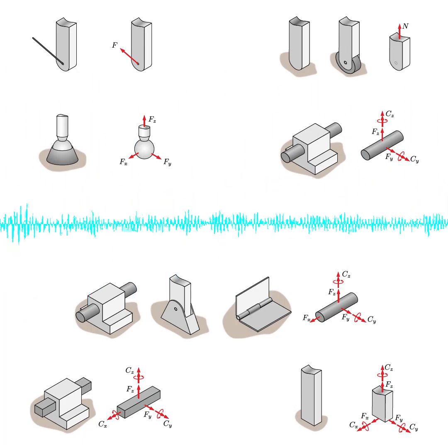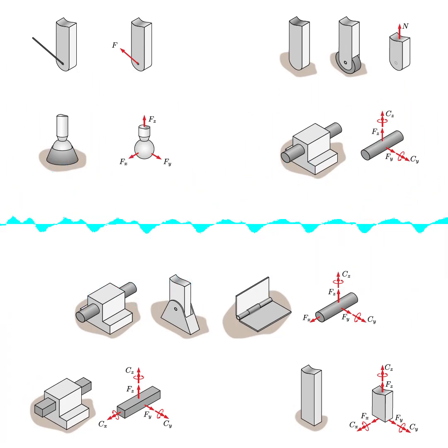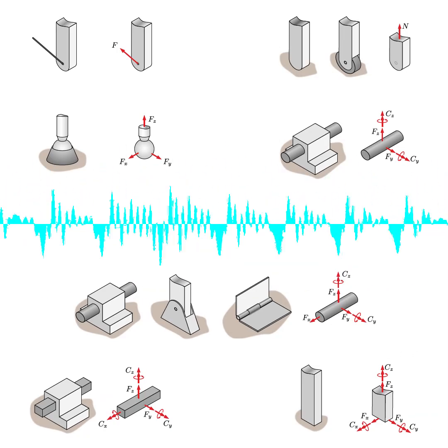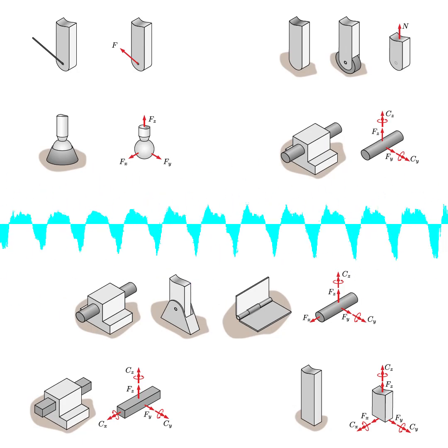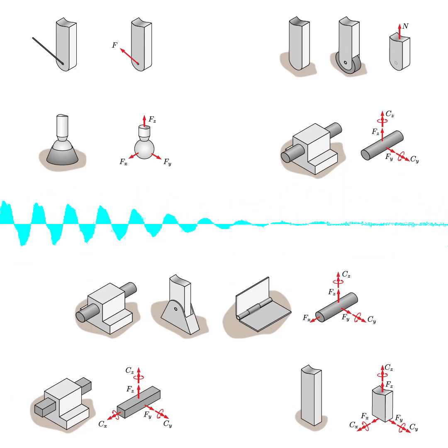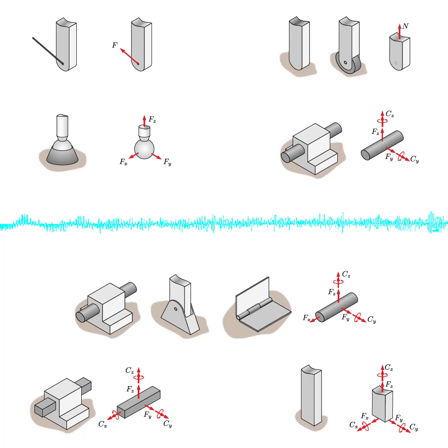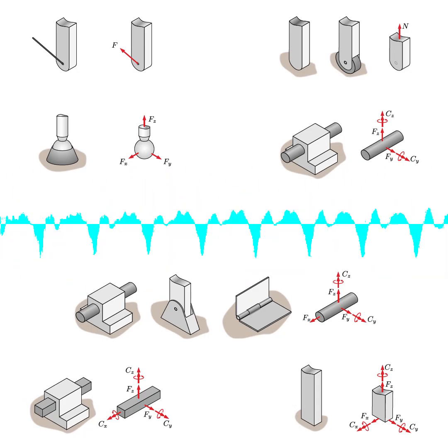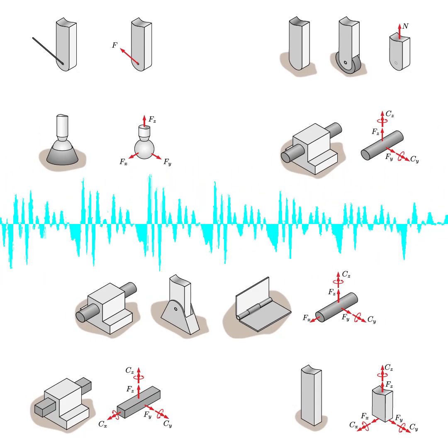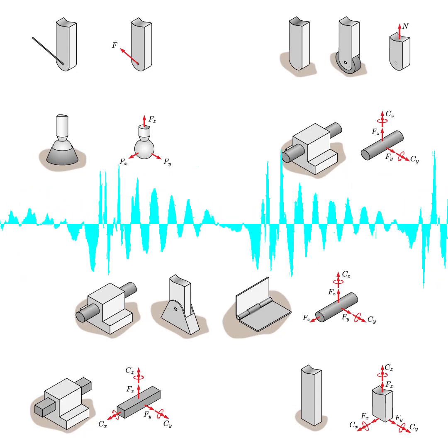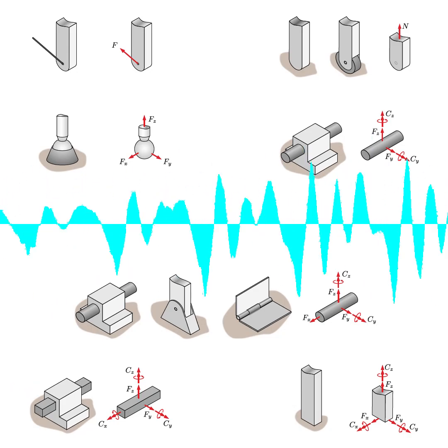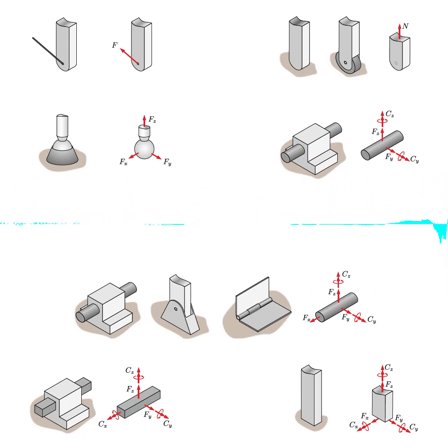Absolutely. The textbook really emphasizes that drawing a correct free body diagram is the very first and most important step in solving any equilibrium problem. Because it's like creating a clear picture of all the external influences acting on the object we're interested in. If you get that picture wrong, then any calculations you do afterward are meaningless. Garbage in, garbage out, as they say. Exactly. Okay, so how do we go about creating this all-important FBD?